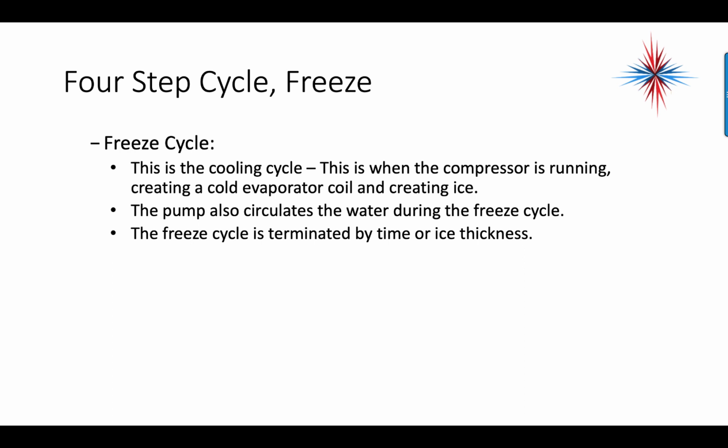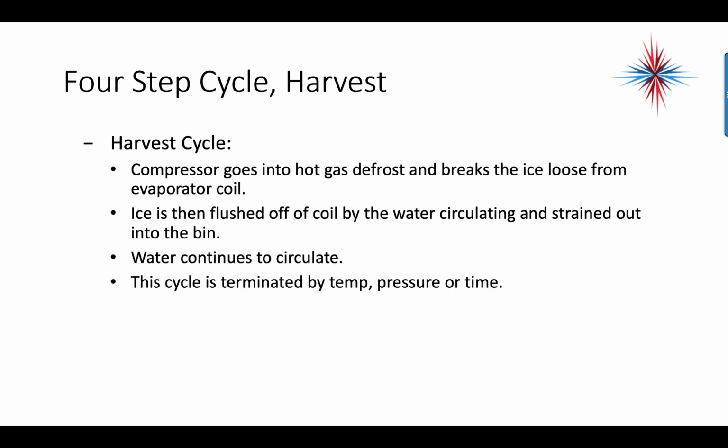The freeze cycle is the cooling cycle. This is when the compressor is running, creating a cold evaporator coil and creating ice. The pump also circulates water during the freeze cycle. The freeze cycle is terminated by time or by the thickness of ice on the evaporator plates.